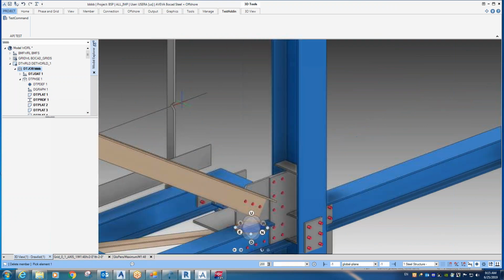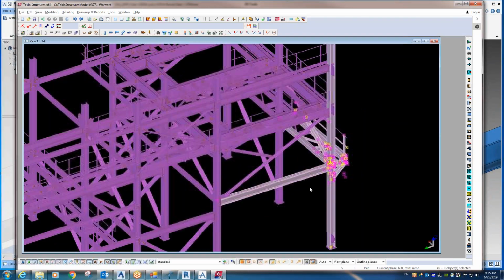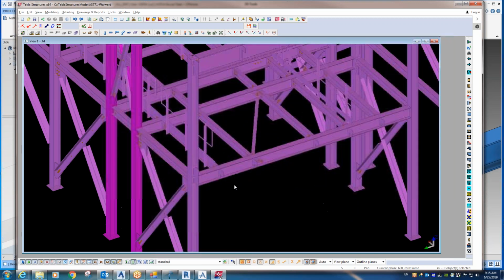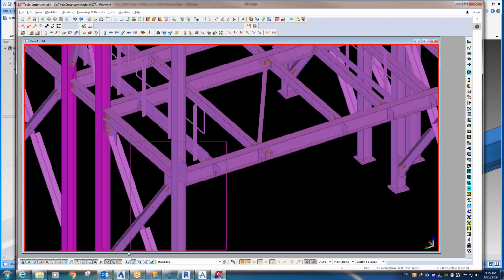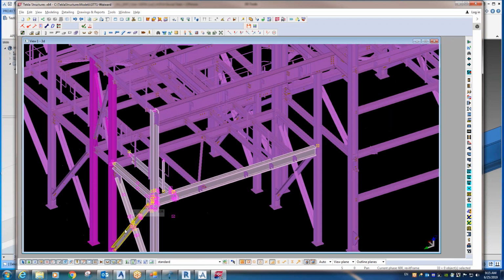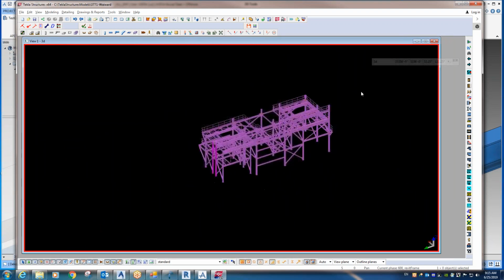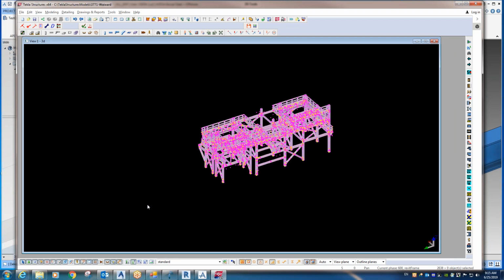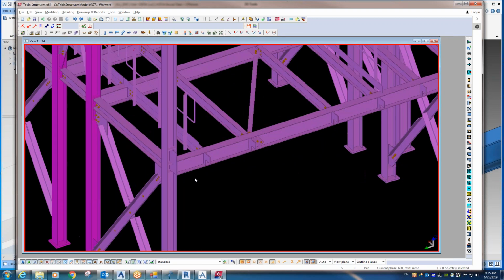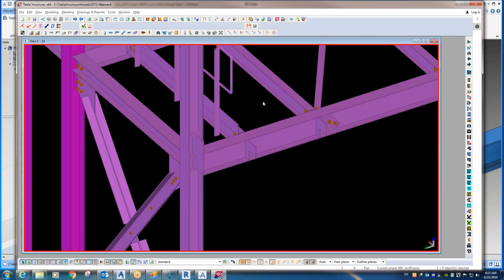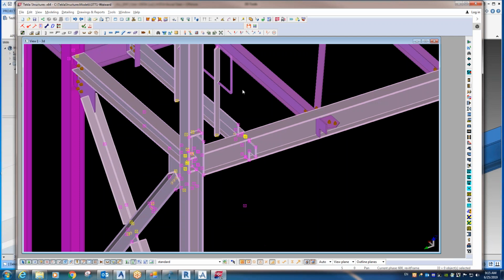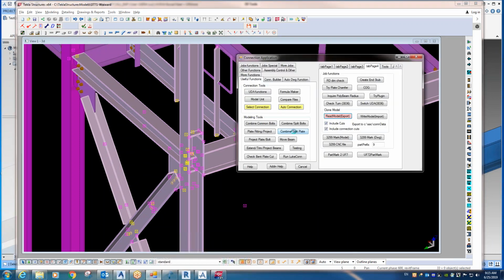So almost we can do anything, whatever we have in Tekla, we can just select them and import to Bocad. I tried selecting the whole face, about 2,000 pieces, and it ran about 5 minutes to import to Bocad, but for a demo that is too long. 5 minutes is probably too long. So I can just try another small area.